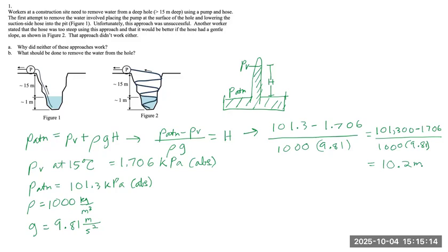because fluid moving through a hose will reduce this height further, as there are also pressure losses associated with viscous forces in the hose, which will counteract the flow of water. A longer hose will increase these pressure losses and reduce the maximum height even further. Therefore, the scenario in figure 2 is even less effective because the hose is longer.